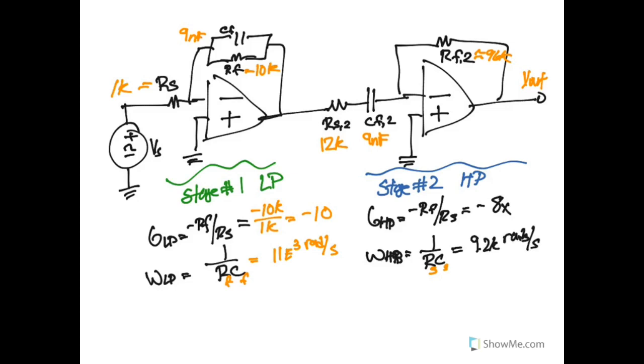And so you might ask yourself, okay, well, you did it in radians, like what actual circuit is this? And so let's go ahead and plot these and try to figure out what happens. So let's say up here at 9,000, we have a high pass circuit. So here is our high pass cutoff. And then our low pass is going to be here at 11,000. So here's our low pass.